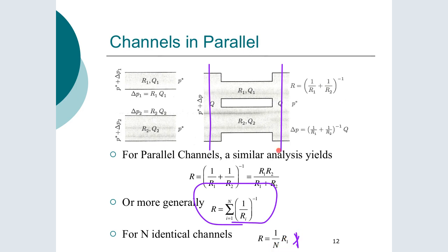So again, there's a way of increasing your flow because you're sending the same flow down each channel, so the effective resistance is reduced. Now, these kinds of calculations, although they're very simple, are very useful in terms of doing design work and doing preliminary sizing of your channels. Because when you go to CFD, you're doing a lot of number crunching, and it's not cheap to do CFD solutions. So very often you can get a decent answer just by setting up an Excel and just running some hand calculations to get a feel for things.